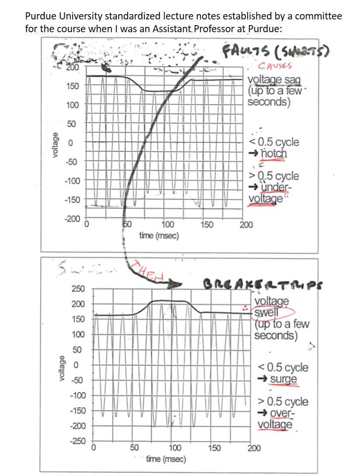Next, we want to consider a sag. So that's just a small drop in voltage, and you're saying, well, that can't be a problem. Well, yes, because everything inside the computer is actually not digital. It's made to digital, but when you have capacitance charging up on a gate or on a signal line, that voltage isn't always going to be exactly 5 volts. Especially if you have fan out, where you have one circuit driving a bunch of others, your signal degrades.